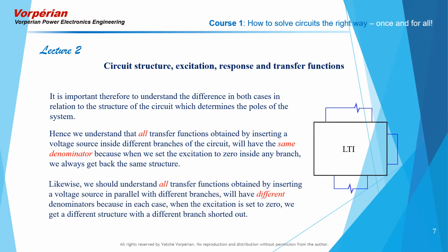Likewise, we should understand all transfer functions obtained by inserting a voltage source in parallel with different branches will have different denominators, because in each case, when the excitation is set to 0, we get a different structure with a different branch shorted out. Very important.